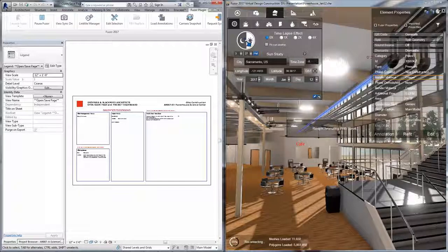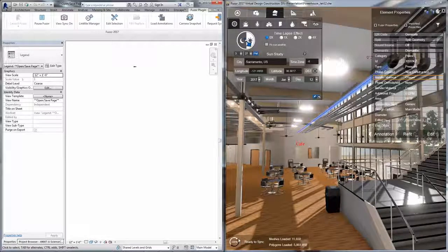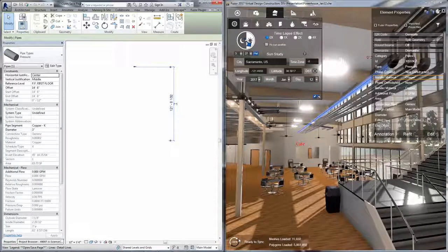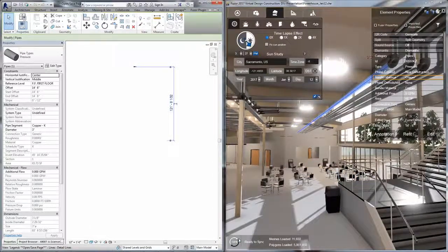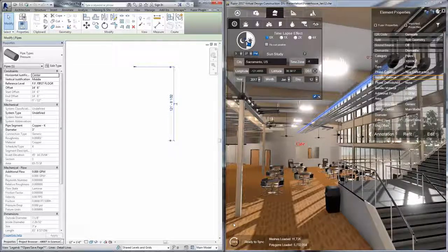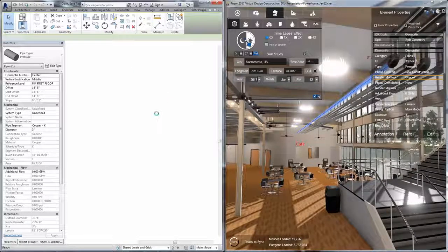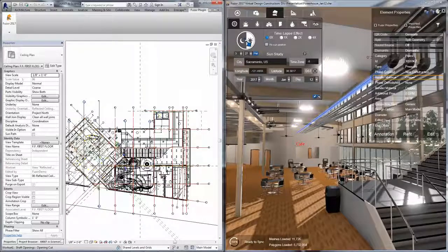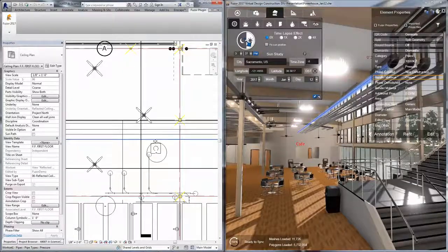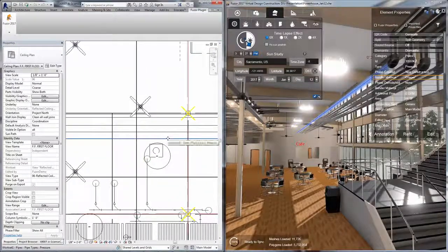So that's just about done resynchronizing. Give that another second to kind of finalize there. And since I am resynchronizing on that, it's going to try to also automatically locate the most applicable 2D view that has that particular file in it. Now I'm in course mode right now, so you might not be able to see it, but this is actually highlighting in blue, which is that pipe.